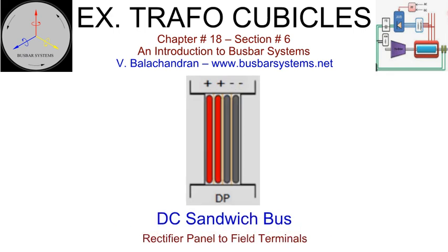The output from the rectifier cubicle is connected to the generator excitation winding terminals. In the past, the DC power connections from the rectifier cubicle to the generator excitation winding terminals were carried out by copper cables. Each pole had several cables running in parallel. Now the DC connections are being carried out with busways with copper conductor. These are very compact connections and suitable for routing near the generator foundations. These connections are extremely sacrosanct and care is required in establishing their reliability.